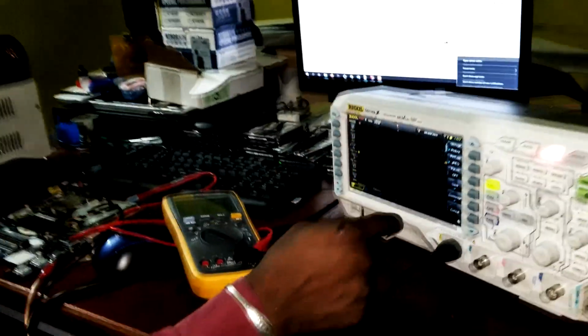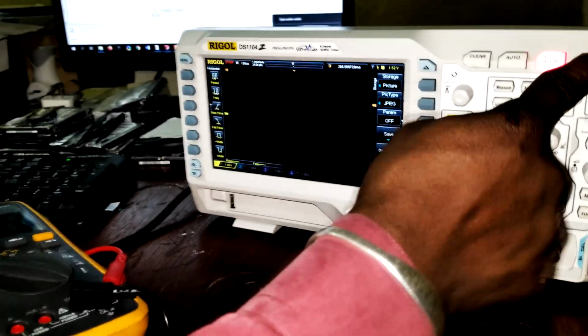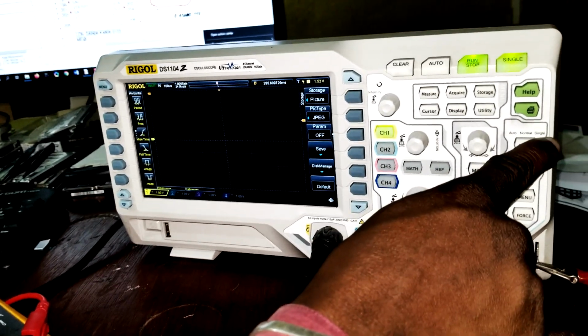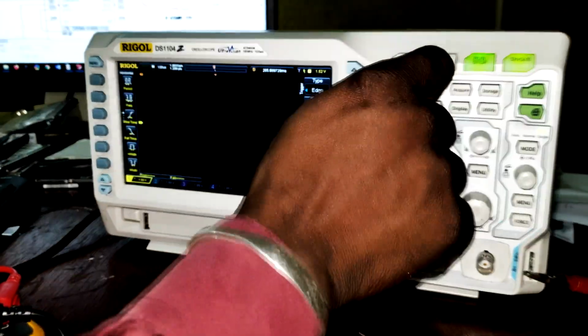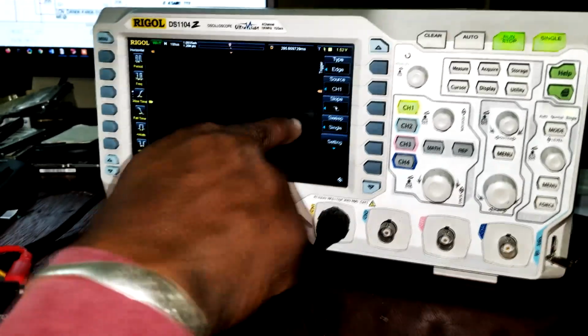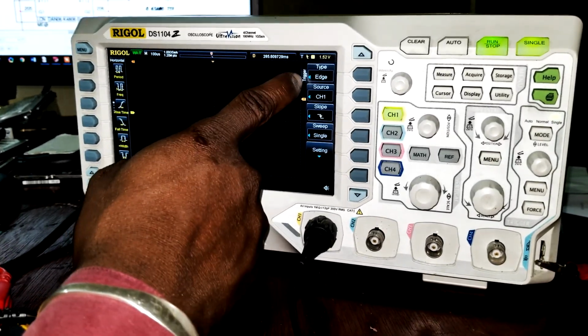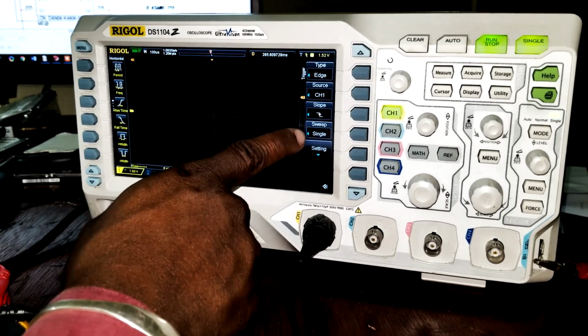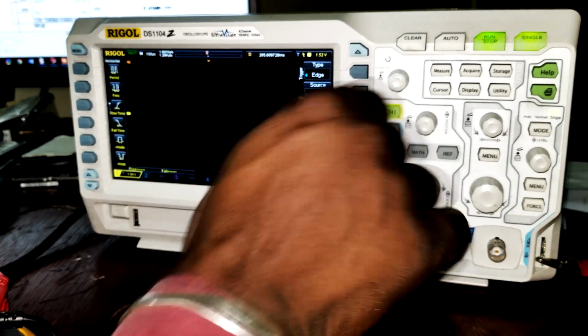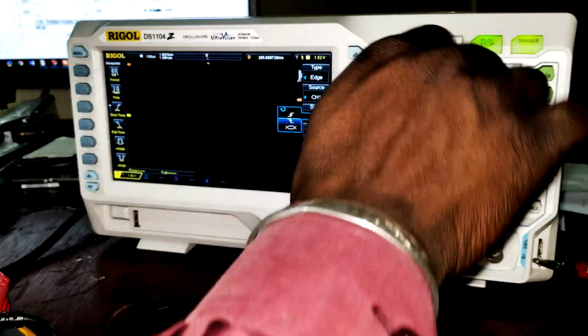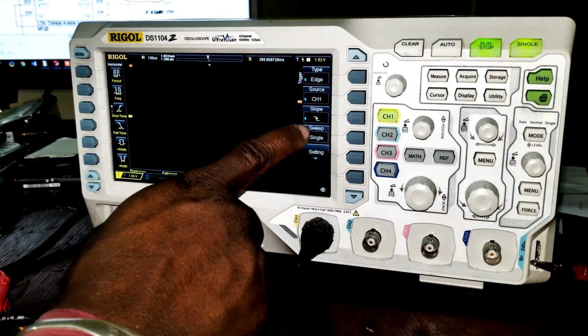So let's clear that. Single trigger, and I'm on single, right? Good. Our trigger menu is here, and we are going on the falling edge. Our source is set to channel 1. Our trigger is set to edge, and we are on the single sweep, right? It's very important that you set this. If your oscilloscope is set on the rising edge...